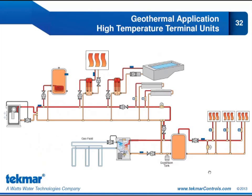So here's an example in this system. I have just about everything on my boiler loop. I have domestic hot water, I have a snowmelt zone, I have a pool, and I have a couple of high temperature terminal units. So it is possible to include all these things into a system design. You can take advantage of those terminal units that are in existence, as long as you make sure that you have a backup heat source that can provide all the necessary heat for these high temperature loads.